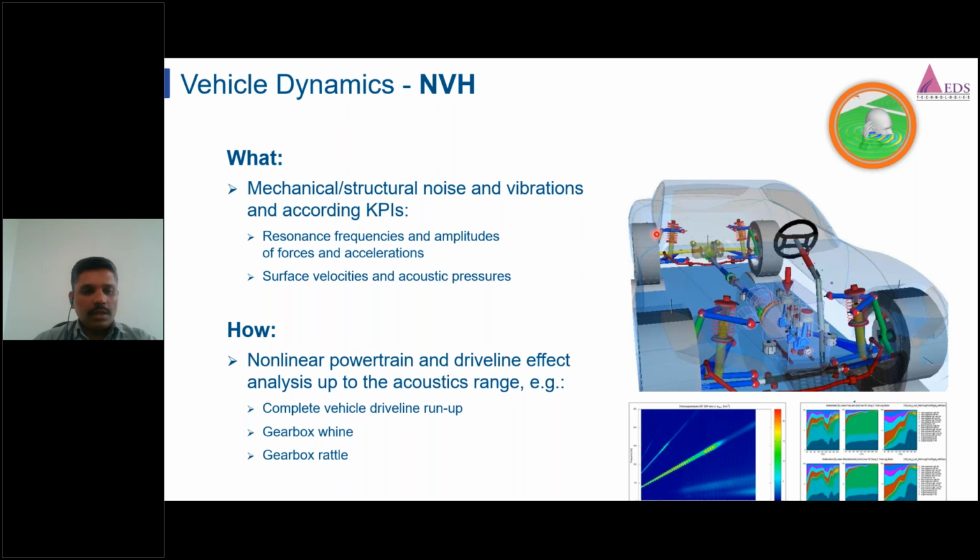And then next, the simulation scenarios like gearbox whine and gearbox rattle. Gearbox whine means a high-pitched, smooth, continuous noise that often increases with the vehicle speed or engine RPM. And gearbox rattle is a more irregular, metallic or chattering noise.